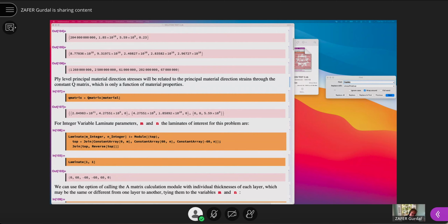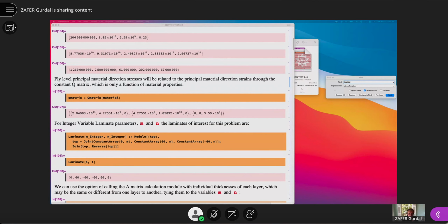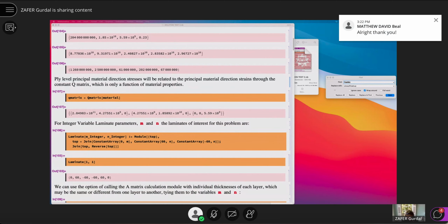the Tsai-Wu diagrams, you can check that your design is actually satisfying the constraints, which, if your constraints are coming from fmincon, they're satisfied. But if your constraints are not right in calling fmincon, and you do the analysis of your final design and find the design point outside your strength envelope, then something is wrong. So the only benefit of these failure envelopes is to be able to tell if you're satisfying all the constraints. Then you don't need graphics for that. You can actually recompute the Tsai-Wu number at the final design. If it's less than or equal to 1, it means it actually satisfies. So that is my answer. Is that all right? Okay, very good.